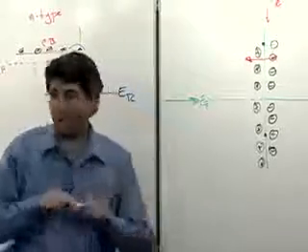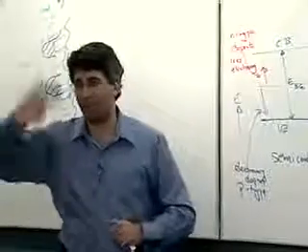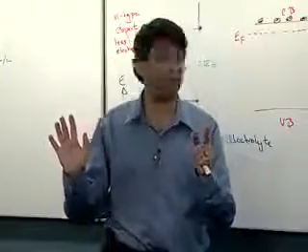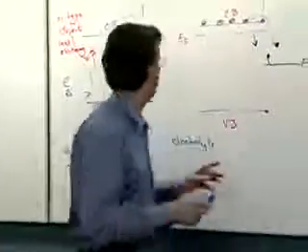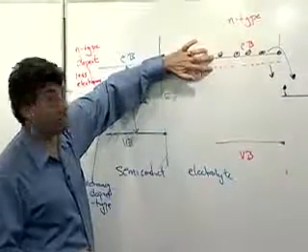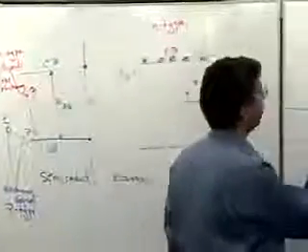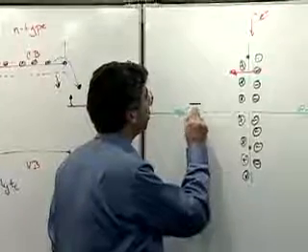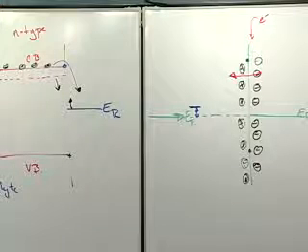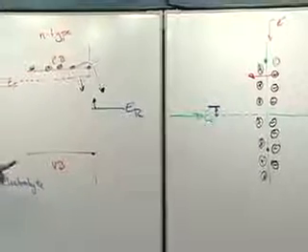Now, way back in the bulk of the semiconductor, since the semiconductor is a lousy conductor, the electrons way back in the bulk have got no idea what's happening on the surface. There's all this excitement going on at the surface, and they're just clueless. Bad communication. Okay, so they don't know anything that's happened. So, if at the beginning of my story I have that energy, the difference in energy between the Fermi level and the conduction band edge, then way back here in the bulk, later on in my story, I have to maintain that energy difference. So my conduction band edge better be down there, the same place as it is up here, if I'm in a frame of reference which is inside the semiconductor.